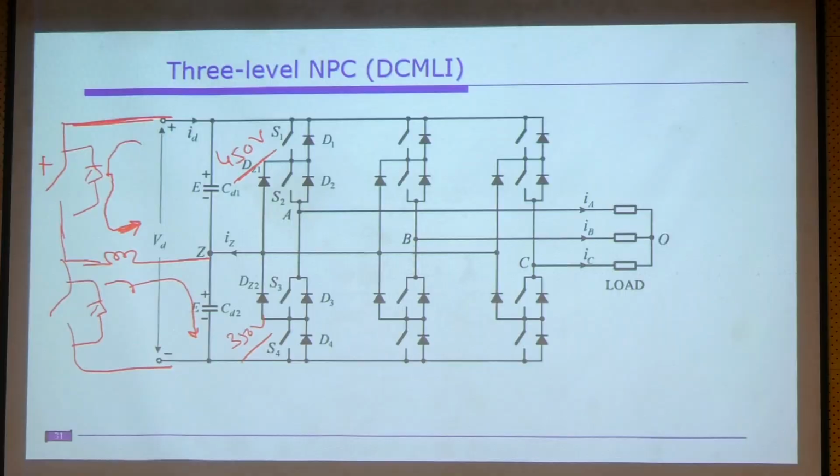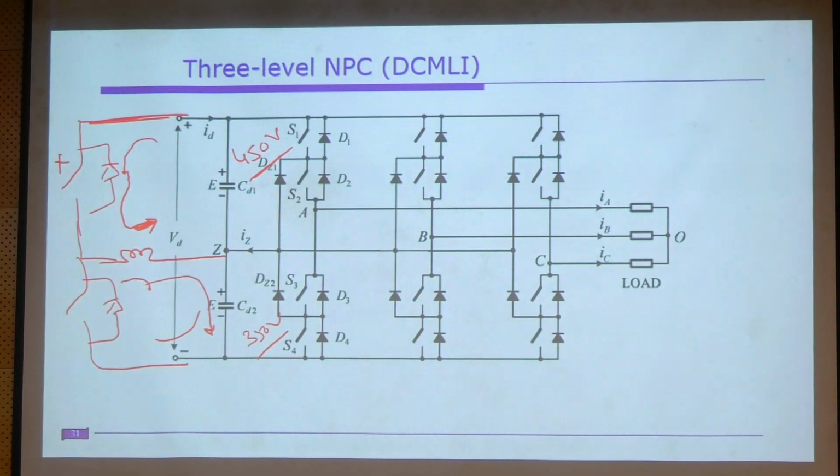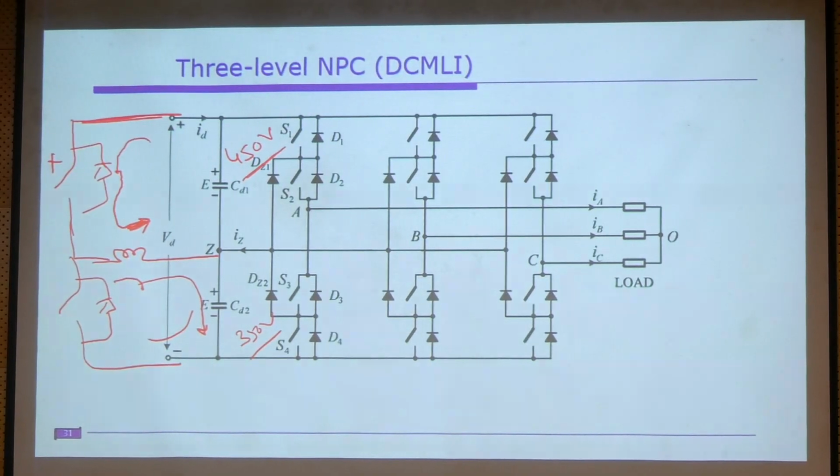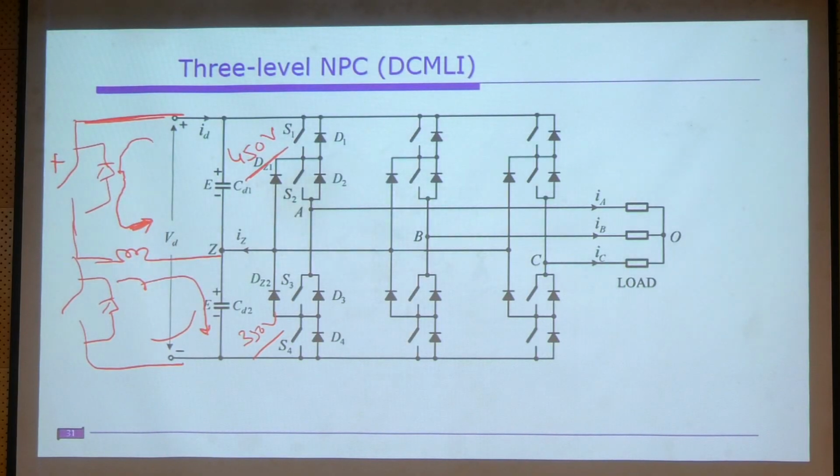So this way you can balance the capacitor voltages by using some additional circuit, which is widely used especially for motor drives or for grid integration in early days. You can connect some auxiliary circuits that transfer from the upper to the lower. Same thing we can do from the bottom to the upper one. If the bottom has excess charge, that particular switch will be turned on and we will turn off the other switch. Once that capacitor maintains its reference value, we transfer the inductor energy to the upper capacitor.